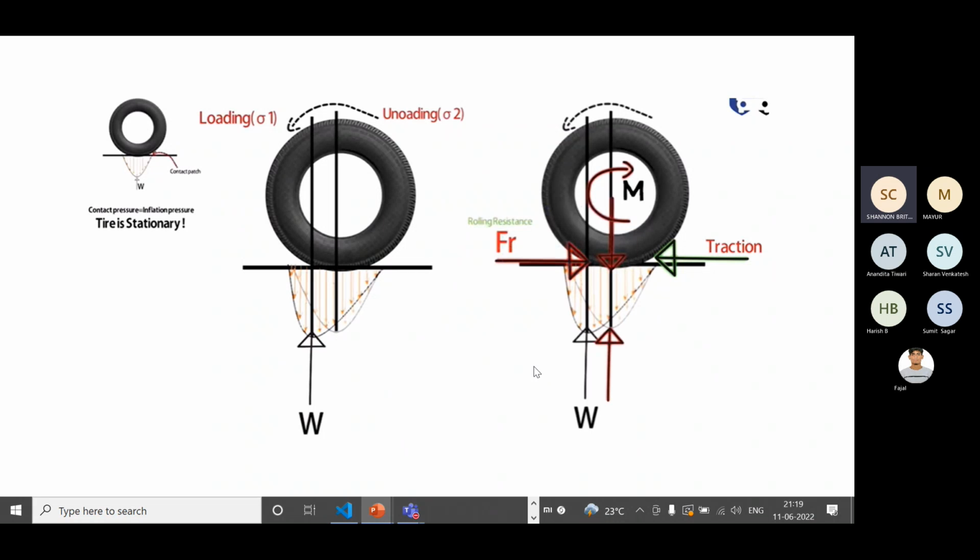So now what we try to do is we try to balance it. So we try to get this to the original position here. When we do that, we can't just put it like that. We have to put a counter acting force here so that these two will cancel and we'll be remaining with the old W. So now we keep this as it is and we take these two forces, and we can see that it will act as a couple here, which is like M, and this is a moment which is acting in the clockwise direction.